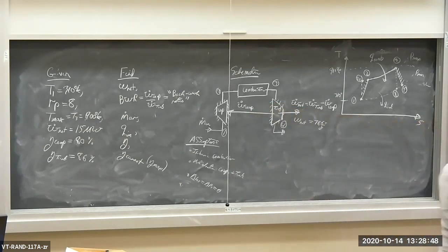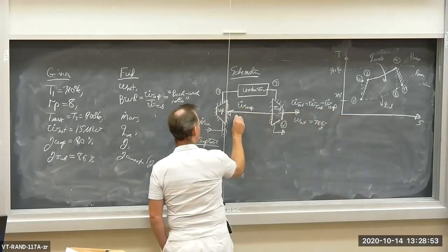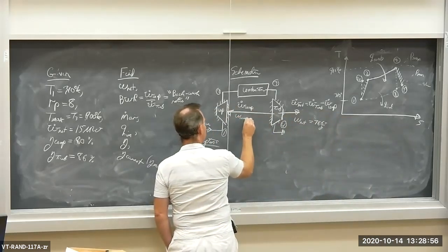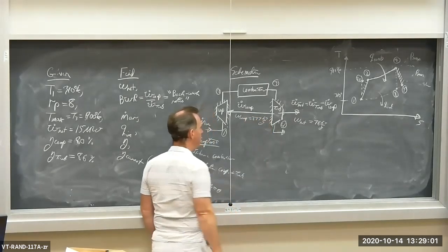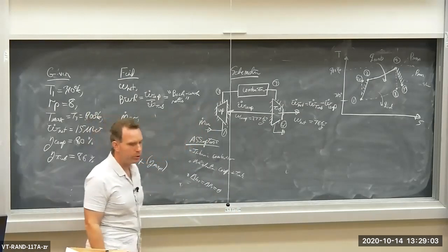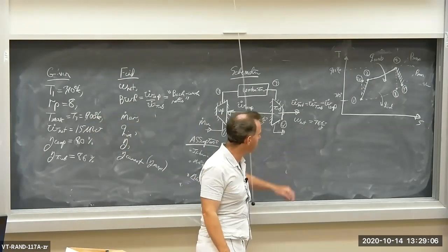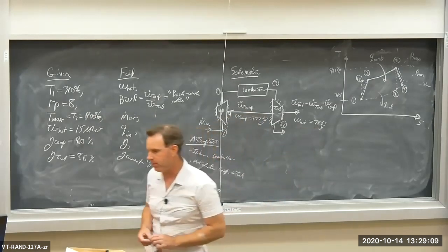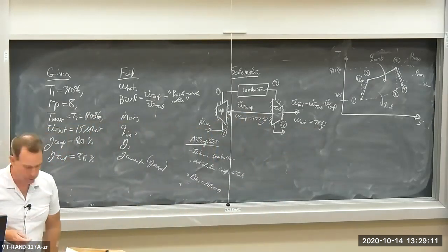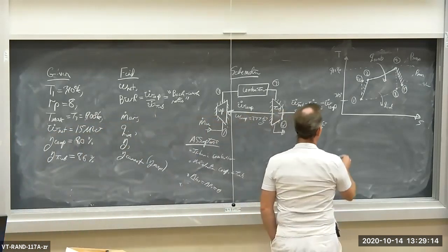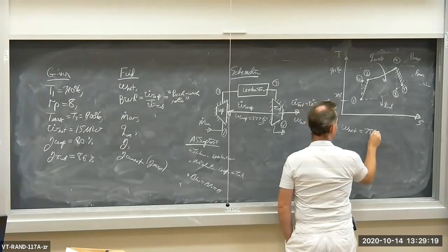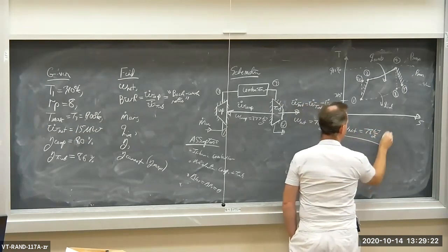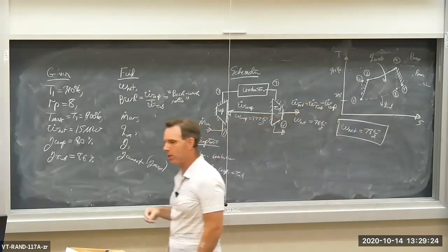That's it. The compressor work, sorry, W compressor is 277 kilojoules per kilogram. And of course, the turbine work is 277 plus 78, which was 355. Okay, so let's box this up somewhere. So W net is 78 kilojoules per kilogram. That's W net.